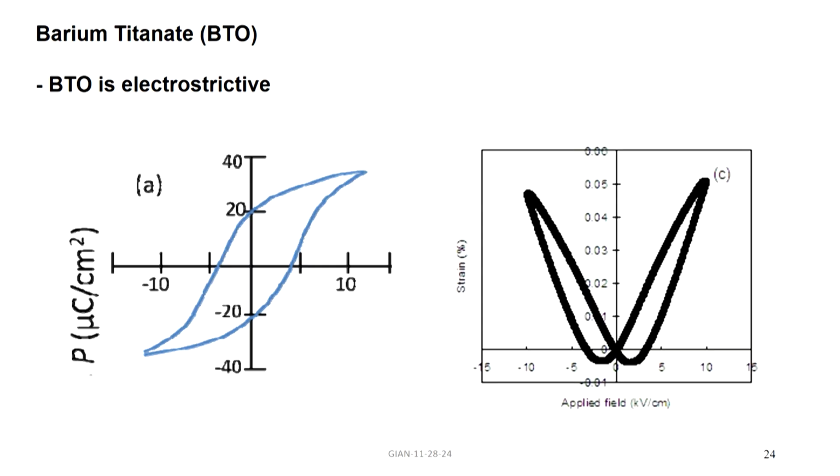So, in our case we use soft PZTs because you want high d33 to achieve a large magnetoelectric response. So, we stay away from hard PZTs, and soft ones are the ones that we use. And barium titanate, it's similar to what I just talked about on PZT. So, the structure is cubic above the Curie temperature. Below the Curie temperature, it has a distorted structure. Barium ions are displaced from the center, leading to a polarization.